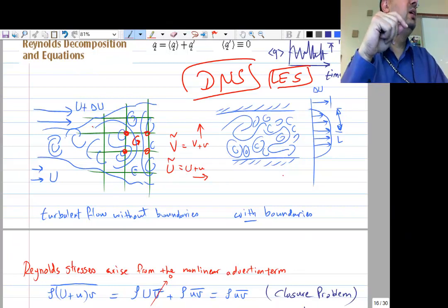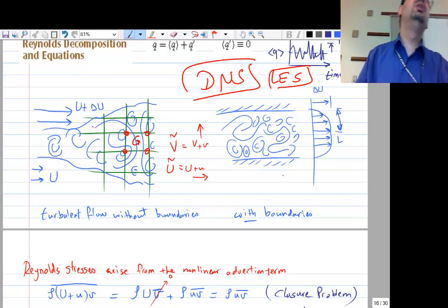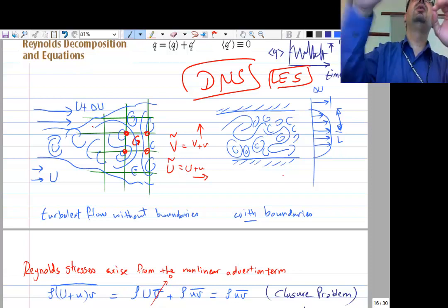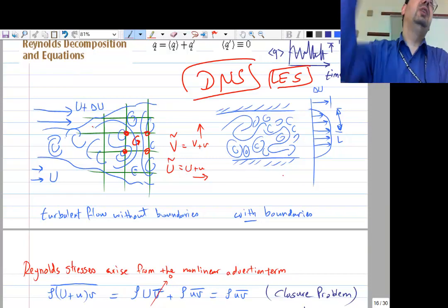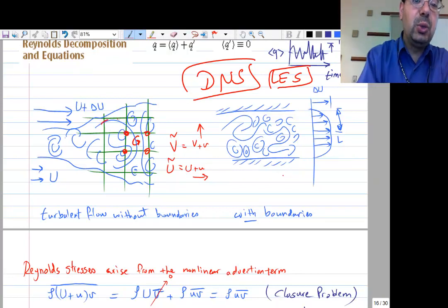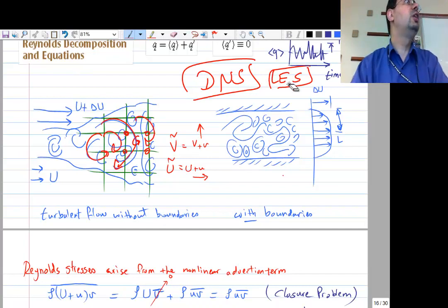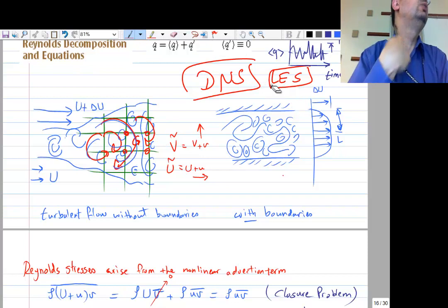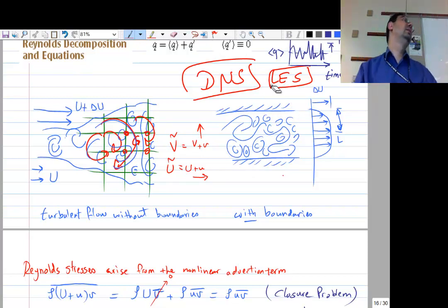They can say, at that Reynolds number, we know the smallest eddies will be that size, we measured them, and they will be dissipating a continuous 15 watts of energy. We know what will happen to them. So let's just make sure the grid is small enough to capture the large eddies, the eddies that we don't really know how they behave. But the smallest ones, we will model their effect. Okay? So this is called large eddy simulation.